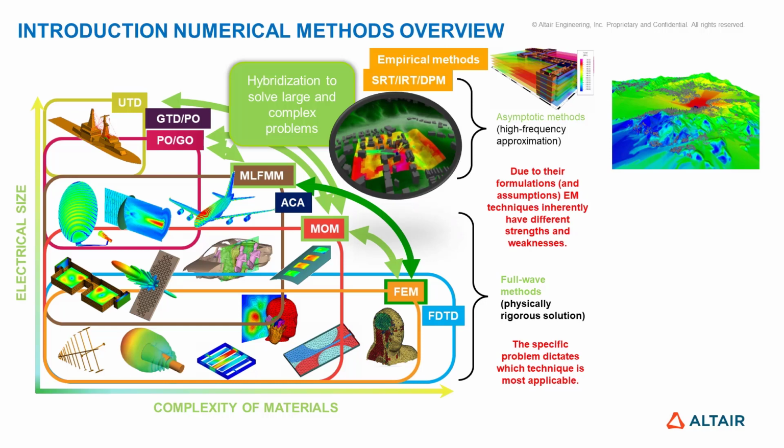But once we move to electrically large antennas or antenna placement on large structures, we move to the multilevel fast multipole method, using a convergence algorithm to make simulations lighter in terms of computational aspects while keeping good accuracy.